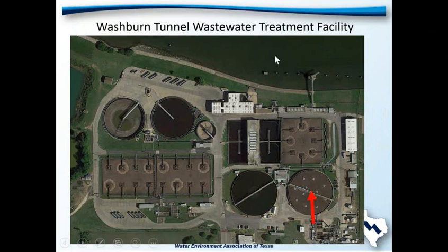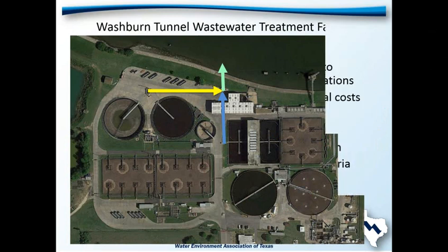Okay, there's two different waste streams that come into this facility. The waste streams that have a large amount of volatile organic compounds go to a first stage oxygen activated sludge plant where the VOCs are destroyed. The streams without any volatile organics go to the primary clarifier. They combine, they're split between parallel activated sludge systems. And prior to this project, they then combined at the outfall and went to the Houston Ship Channel. One thing you'll notice from this aerial, there was no existing end of pipe disinfection system at the facility.